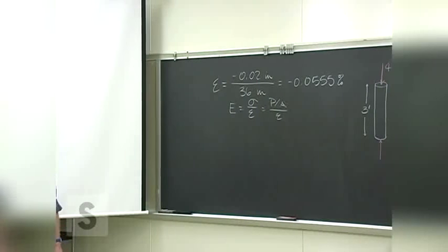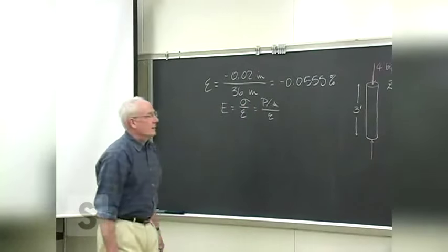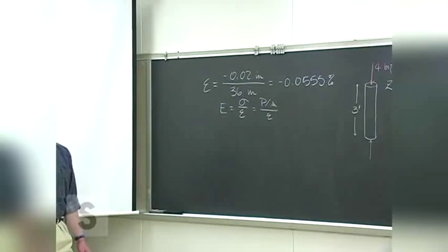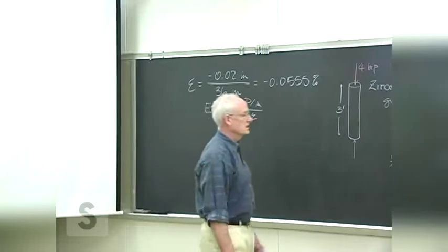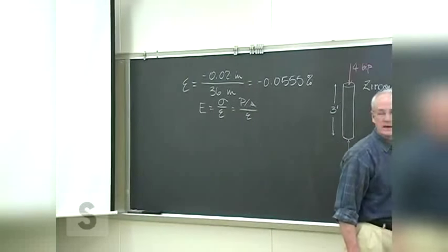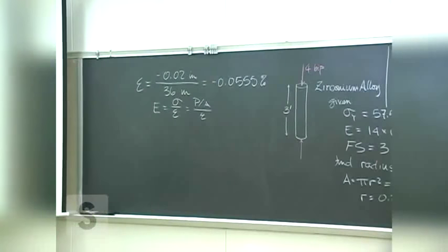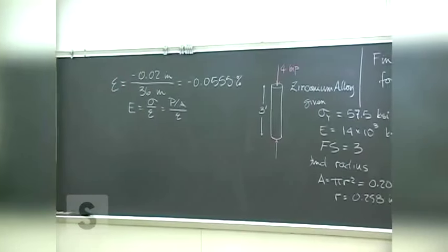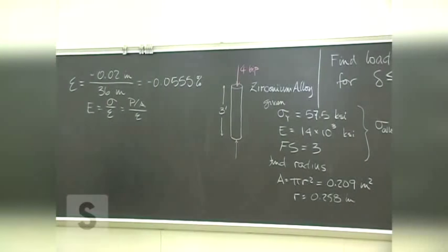Get a 1.62? Okay. Remember, though, big factor of safety on that, so if it's 1.62, 1.63, it makes no difference because you're way, way under what the limits were by applying this factor of safety. So that's a very typical way the factor of safety is applied, is right on the material properties themselves.